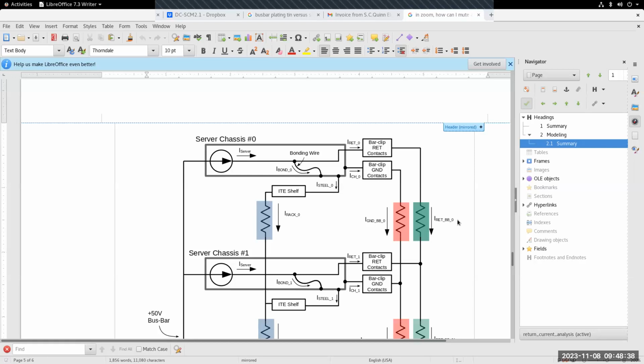Okay. So this came up in my design organization because we were just trying to decide up front whether we were going to use isolated or non-isolated DC to DC conversion coming right off the bus bar. That's why we investigated this. If we go non-isolated and it's just really the unified ground, then current's going in all over the place, and we need to think about that.